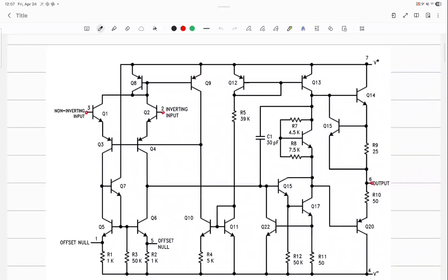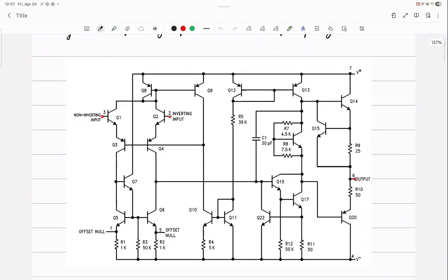Because of the internal circuitry of this guy. If you measure the input resistance of an op-amp by connecting a multimeter or doing a circuit analysis, you will see that the input resistance is very high, in the order of mega ohm, okay? So because in this course we are considering an ideal op-amp, which means a very simplified version of op-amp, instead of assuming that it's in mega ohm range, we will consider it to be infinite, okay? So the input resistance is infinite.